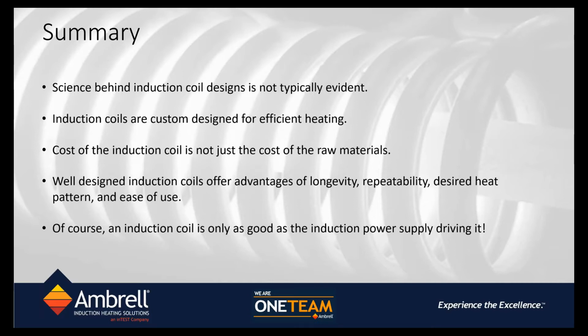Now, induction heating differs from resistance heating in the fact that induction heating heats into the depth of the metal that is being heated. So in a pancake style coil, we actually heat into the depth of the metal plate. So depending on how thick the metal plate is that you're trying to heat, the perceived heat pattern on the top surface can be really good looking or really bad looking.